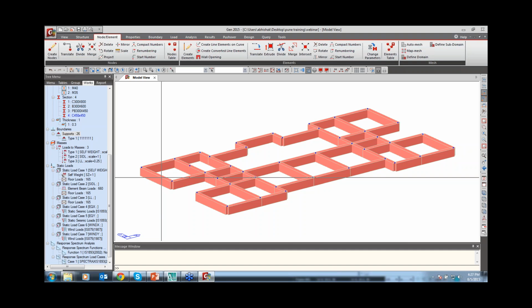Now Chetan sir is asking one more question. Is any boundary condition applied at the origin of the floating columns? No sir, no need to generate any boundary condition. The only thing is that you have to neglect the diaphragm effect. If you consider the diaphragm effect at that particular point, it gives the wrong result. So if you are using other software also, do not consider the diaphragm effect where your floating column starts.